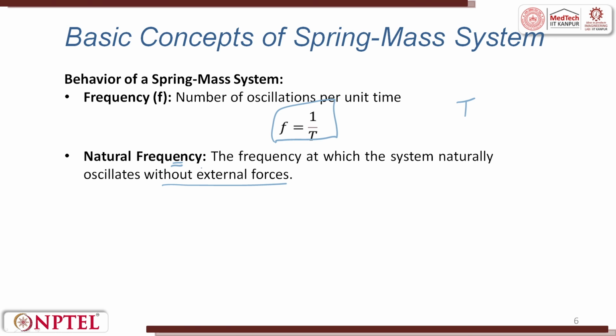So, how will you change the natural frequency? The frequency can be changed by changing the stiffness. How will you change the stiffness? The material can be changed or the design can be changed. Based on that, to some extent the stiffness can be changed. Predominantly we go around changing the material.